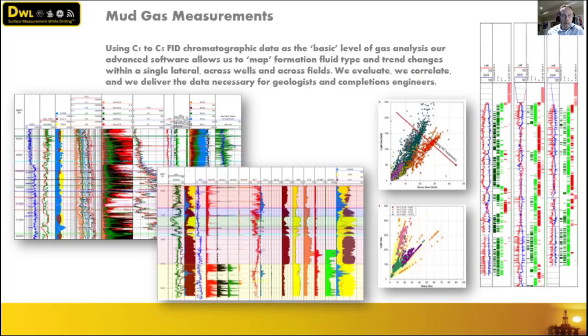You know, the mud gas measurement molecules are also very important. We're typically measuring C1 to C5, in some instances wider spectrum up to C10, and including inerts: helium, hydrogen, nitrogen, CO2. But what we can do with that information, particularly with rigorous QA/QC using gas well drilling methodologies, where we take some of the hydrocarbons from the chromatograph, compare it to the total gas, two independent measurements, we're looking for a good coherence. Typically they should fall within 0.8 to 1.2 compared to the reference of 1,